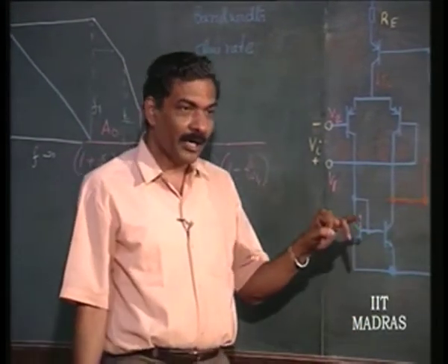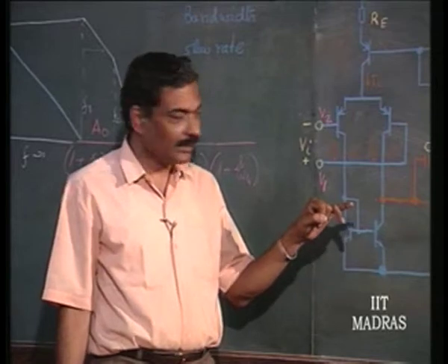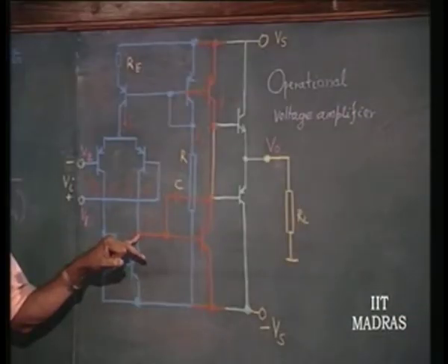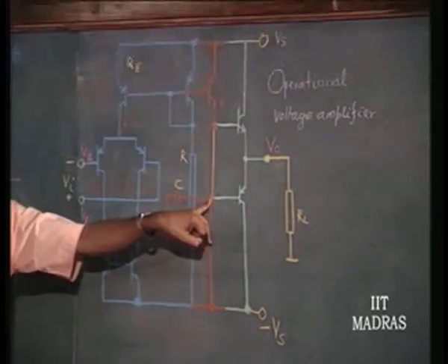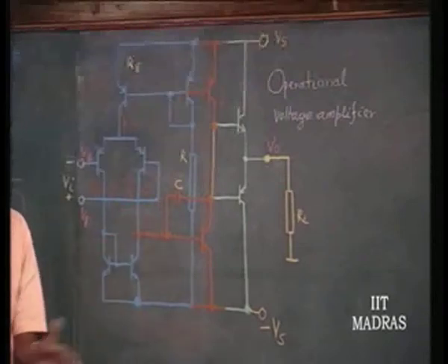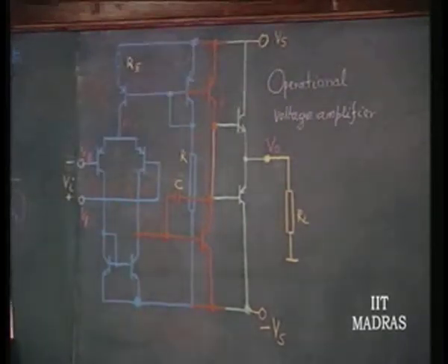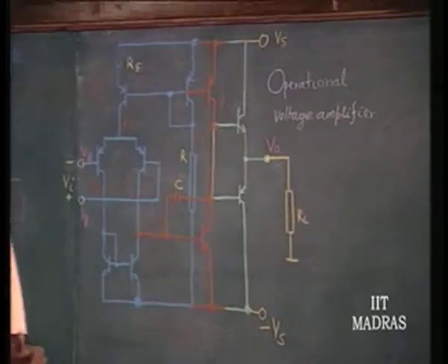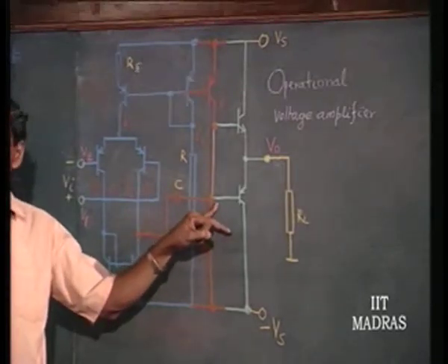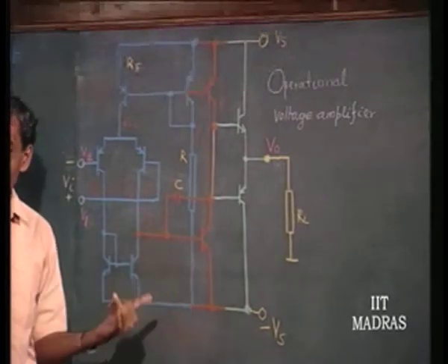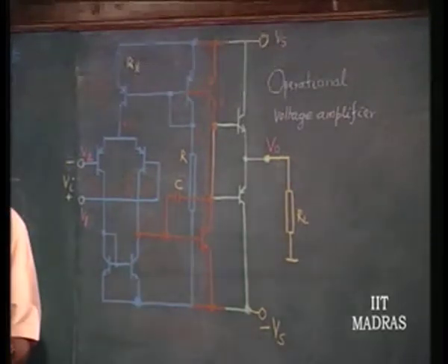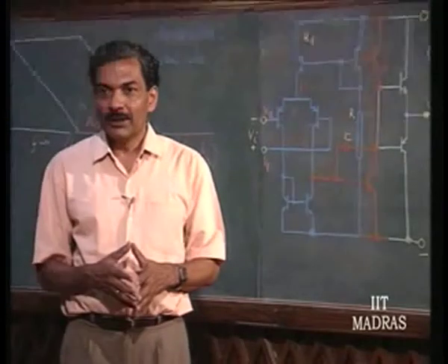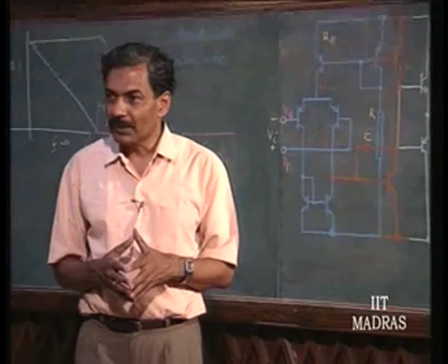Now, the two high impedance points available straight away for you inside the structure are this one and this one. Those high impedance points should obviously have a signal phase shift of 180 degrees, so that the connected capacitor will result in negative feedback. So, this capacitor comes into the picture as what is called the Miller capacitor, that is another way of looking at the thing. Because you are connecting it between two high impedance points, at the input it will come as a huge value of capacitance.